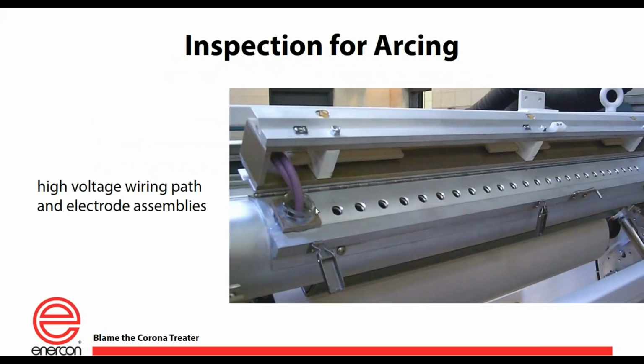Lastly, you want to check for inspecting for arcing. Arcing is simply that, where Tom mentioned, it's going to be looking for the easiest path to ground. When it is found, it'll certainly arc to that, rather than the ground roll where you want it to go. Carbon tracking is one of the visual inspections of a high voltage arc, and it can be caused by dirt buildup, damage to the electrode components, or excessive moisture in the air. It can occur at the electrode mounting tabs, the insulating shroud, the mounting block, or even the high voltage wiring.